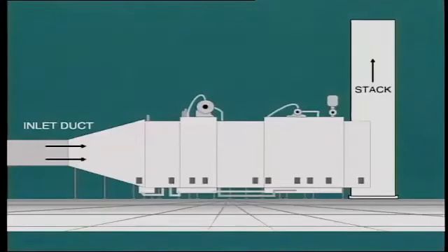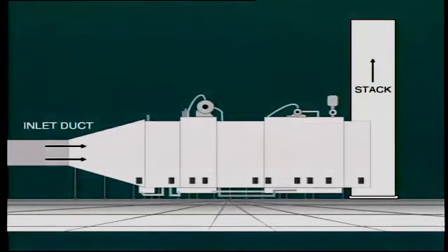Another feature of the lower gas temperature is that it effectively reduces the superheat steam temperature that can be achieved from the HRSG. Most HRSGs operate with a final steam temperature of 850 to 950 degrees Fahrenheit. In order to make use of this gas at the lower temperature end, it is quite common to construct a HRSG which incorporates several independent pressure levels.